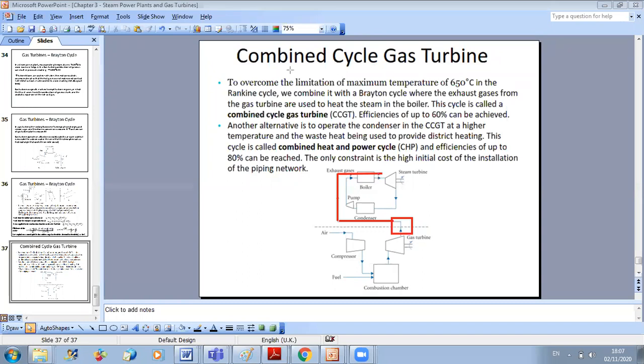How do we calculate the efficiency in this case? If I want to calculate the efficiency of the combined cycle, first, at which level is my heat input? At the combustion chamber of the gas turbine. Here I am heating by combustion of fuel. This is Qn. Since for the steam cycle I'm just using the excess heat rejected from the gas turbine, I'm not putting any extra input there. So I just have Qn in the Brayton cycle.